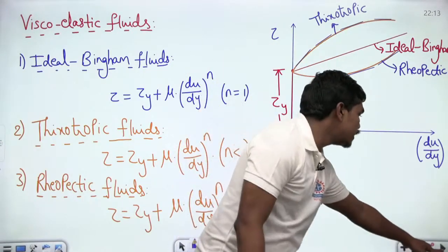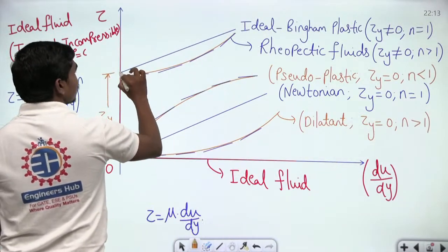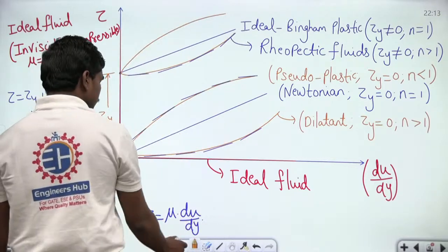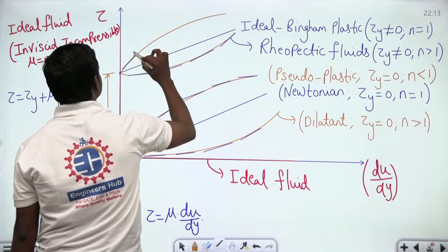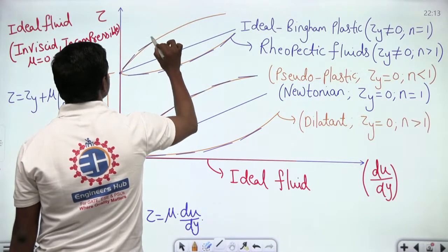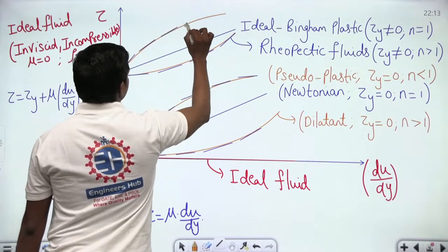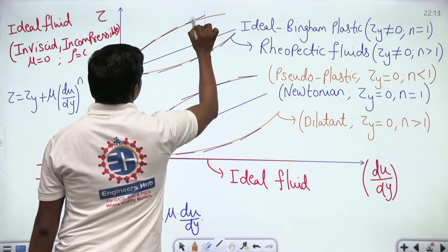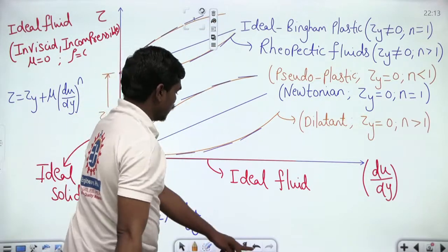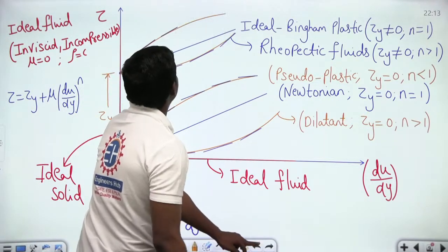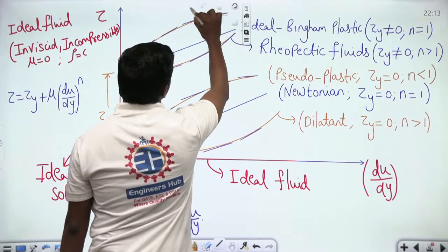in this case, in the thixotropic case, definitely your fluid starts decreasing its apparent viscosity as your time keeps on increasing. Correct? So this is how it looks, and generally in the initial stages you will be experiencing a bit of high viscosity because of this high slope, and of course as your time increases, this viscosity keeps on decreasing. Okay, fine. So you can clearly see here the slope keeps on decreasing. This is the case of thixotropic fluids, correct?